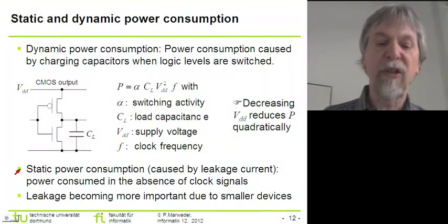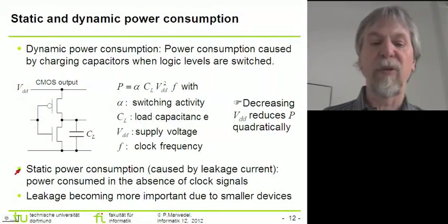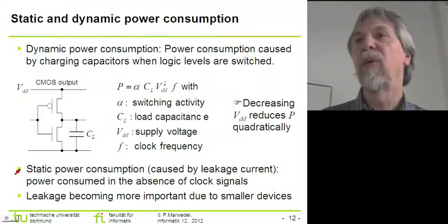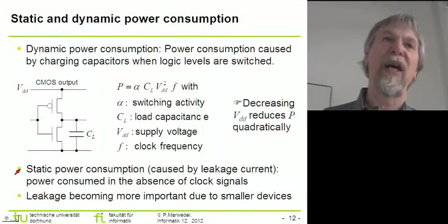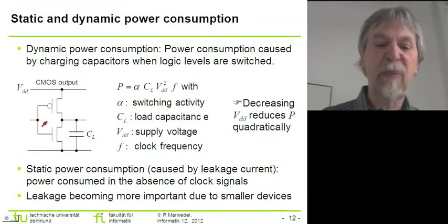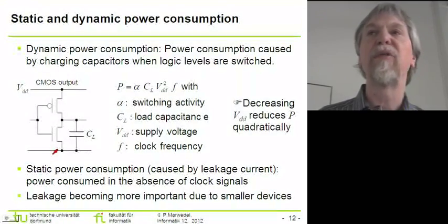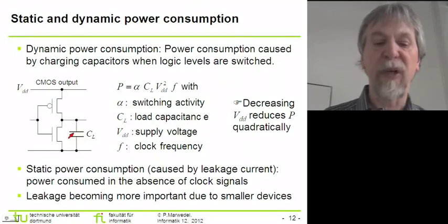And then in addition, we have to look at the so-called static power consumption, which is a power consumption that takes place even if we don't apply any clock signal. And this happens because there is a certain current which is flowing through this path from VDD to ground, even if we are not charging this capacitor.